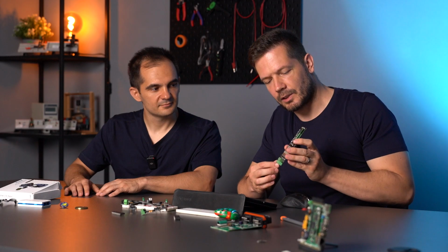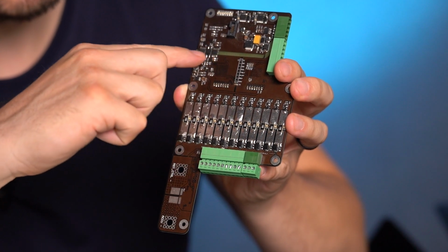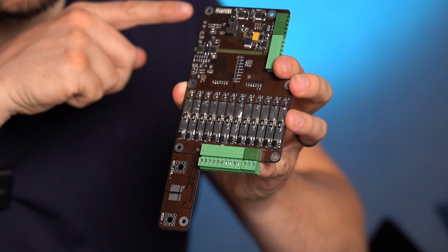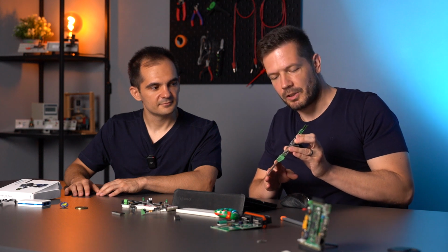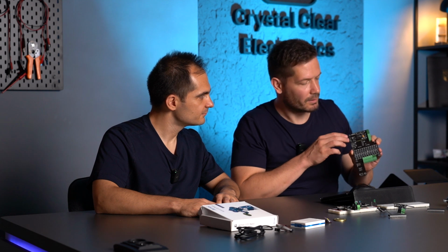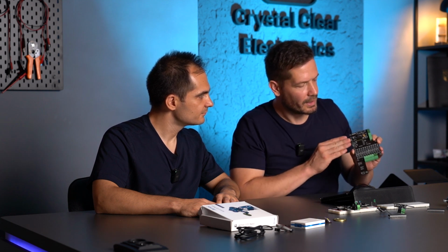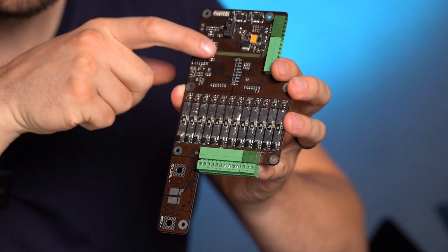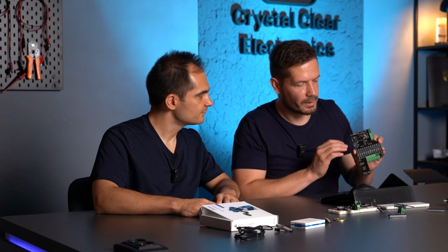Then, interestingly, there is a break in the PCB. This is because the 12-cell battery is expected to operate at a voltage of 50 volts, and we don't want these 50 volts to be able to be transferred one by one to the other part of the battery, where there are more sensitive components. So this part is isolated from the 50 volt part by optical or other coupling ICs.